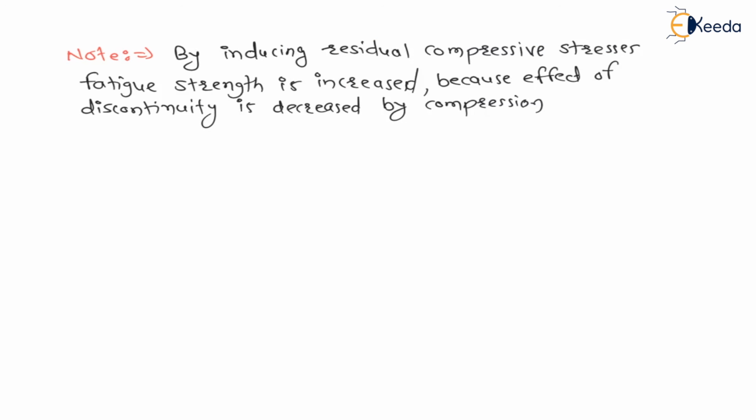Now a very important note in this topic is, by inducing residual compressive stresses, fatigue strength is increased because the effect of discontinuity is decreased by compression. Now to understand this note, let us say one component is there, and there is a notch on this component. Like this, there is a notch on this component, and this notch is nothing but a discontinuity, right? Here there is a discontinuity.